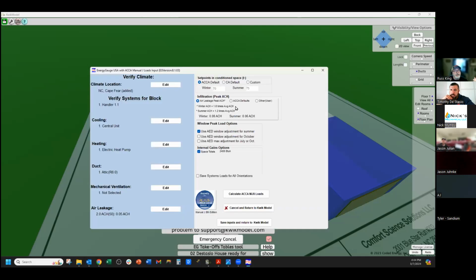If you click here, you'll get those choices that Tim talked about earlier: tight, semi-tight, average, semi-loose, and loose. But if you enter a number down here in air leakage, you want to click that and tell it that's what you want to use. Okay. And then that's pretty much it. It does the AED, the automatic exposure diversity, for you. And that's pretty much it.